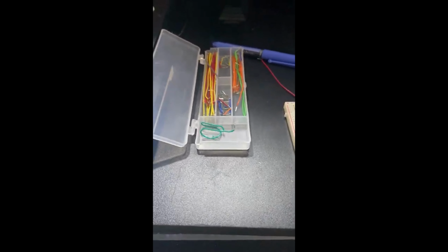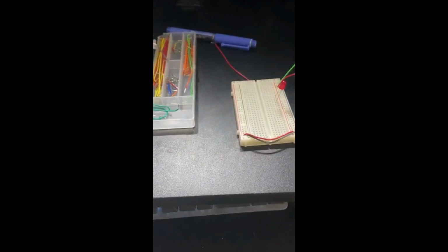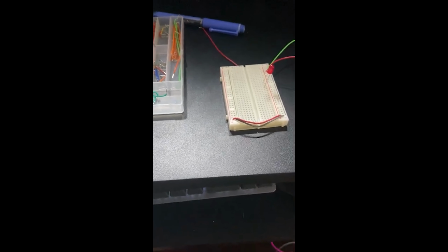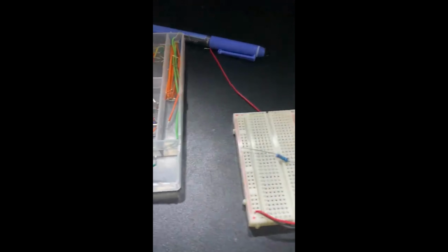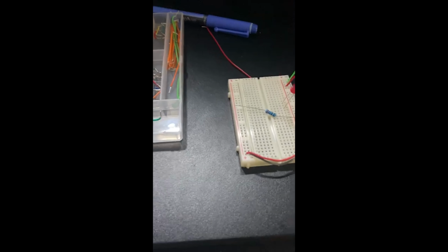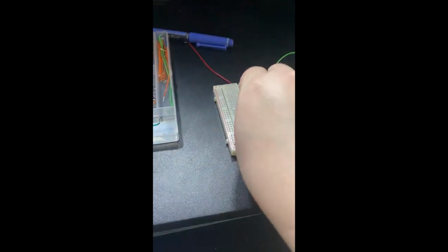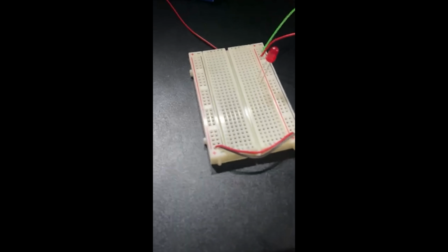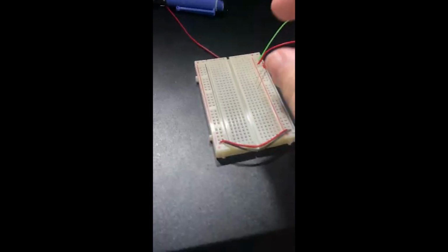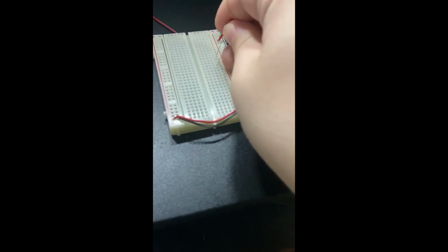So I've got right here some 220 ohm resistors. We can have a variety of resistors for what we're doing here. Sometimes we may want bigger ones or smaller ones, but basically the more resistance that the resistor has, the less electricity can flow through the system. So I usually find somewhere between 200 and 300, give or take, ohms is generally pretty decent for an LED. So we'll use this a lot. Okay, the long lead is facing me.